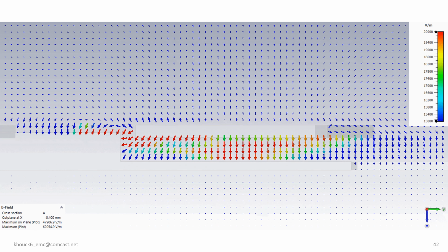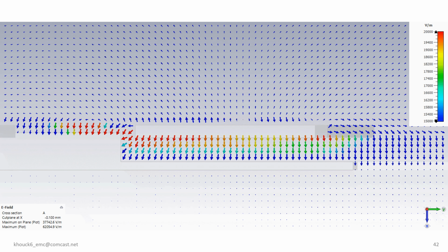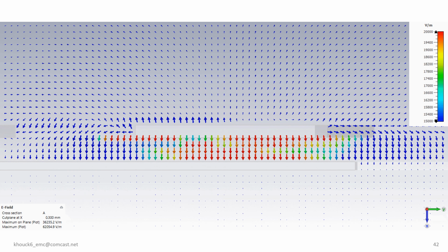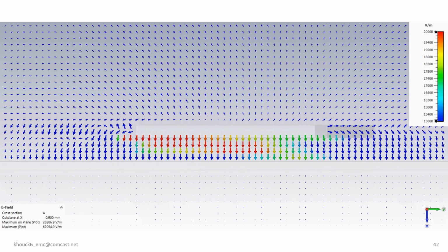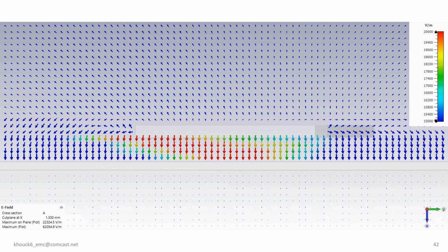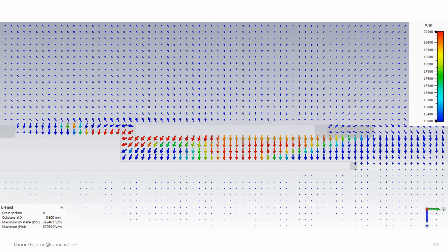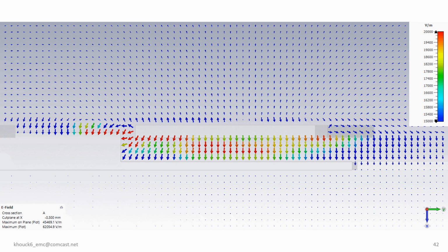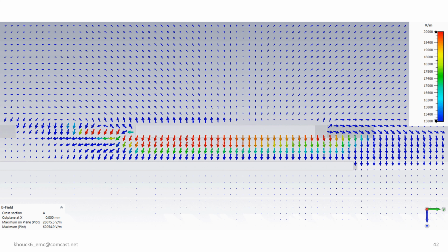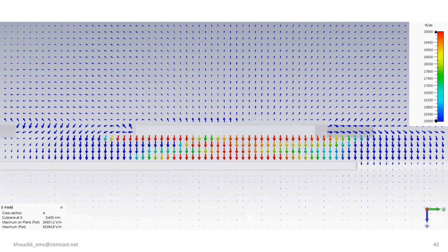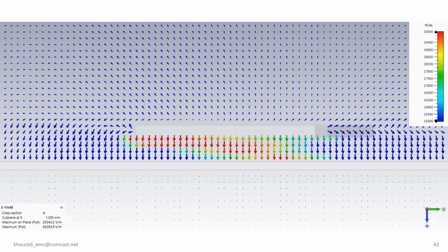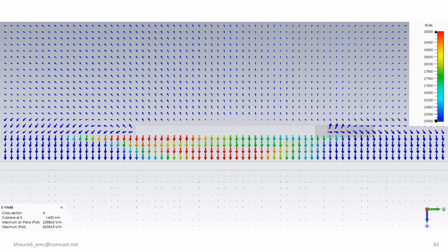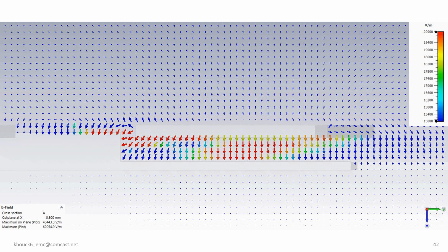By ensuring efficient propagation of field energy from the pin to the space between the signal pad and the reference plane, signal propagation can occur with minimal distortion. The animation illustrates the relationship between conductors separated by an insulator, focusing on a pad structure chosen for this specific application. This structure connects the return pin to the reference plane before reaching the connection point on the signal pad.